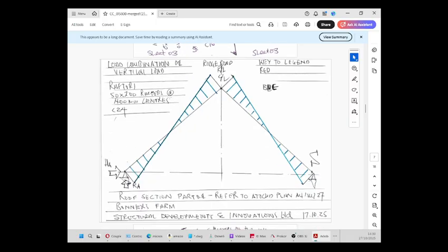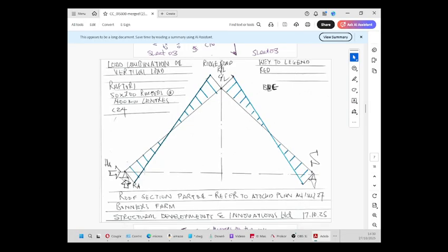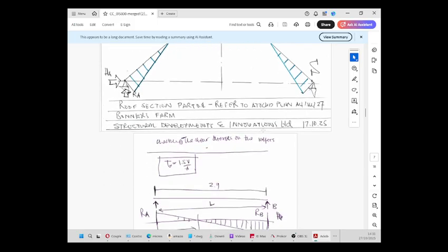So now we're on to the shear stress. Again, I think that the shear stress will look like this. On the rafters, it will be RA will be max, and then at the ridge it will be max, and it will be equal but symmetrical. The rafter will be 50 times 200 rafters at 400 millimetre centres again. Just the vertical combination load 1 shear forces.